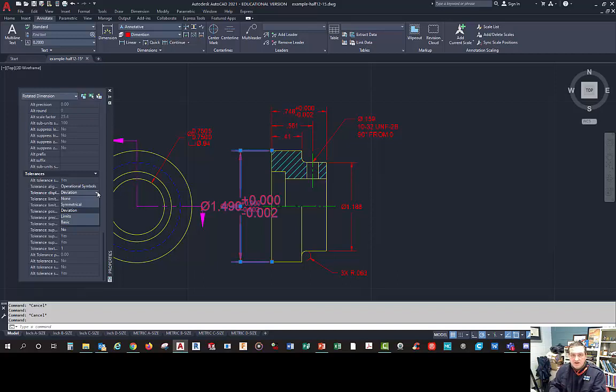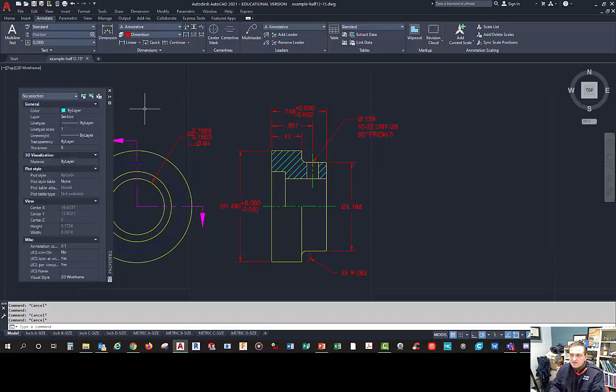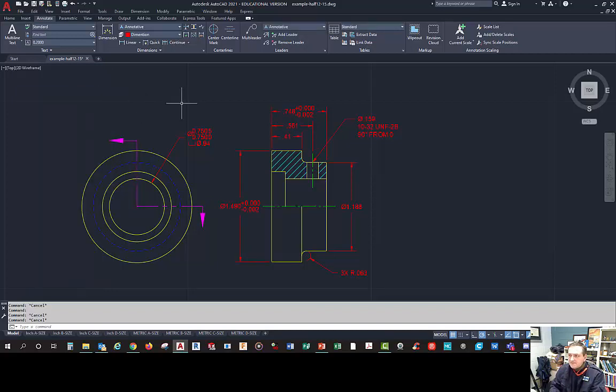And you don't have to create your own style. All you do is put the dimension on there like you're supposed to, get out of dimensioning, pick this, right click, go to properties, and then go down to tolerancing and adjust what you need to adjust. And it'll be fine. That's all I did. Mr. Anderson helped me. He did a good job because it's been a while since I had done this, and I can still do it.